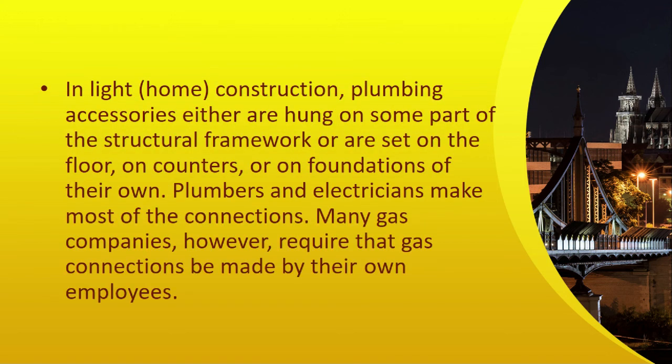In light construction, plumbing accessories either are hung on some part of the structural framework or are set on the floor, on counters, or on foundations of their own. Plumbers and electricians make most of the connections. Many gas companies, however, require that gas connections be made by their own employees, and all gas companies inspect gas connections within a structure. Each accessory is tried and tested for proper operation and the absence of leaks.